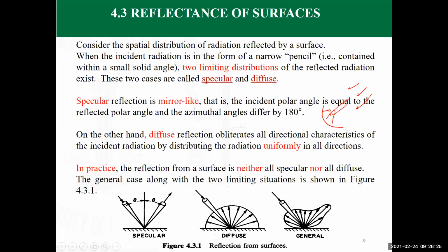So the property that I need to be maximized for this surface is the reflectivity. I don't want it to absorb any energy as much as I can, and definitely I don't want it to transmit the energy. That's why it's not made of glass or glazing. It is basically made of a shiny surface so that it would reflect the maximum possible radiation into a certain focal point where I'm putting a tube.